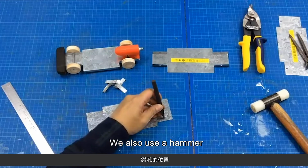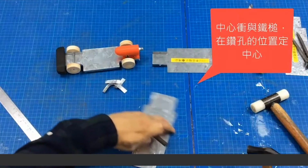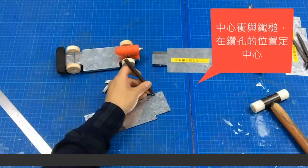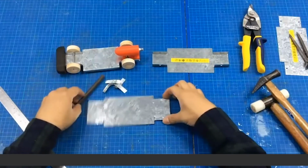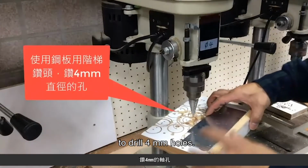We also use a hammer and a center punch to mark the position of the holes. This positioning method can guide the drill for a more accurate drilling. We use a step drill bit to drill 4mm holes.